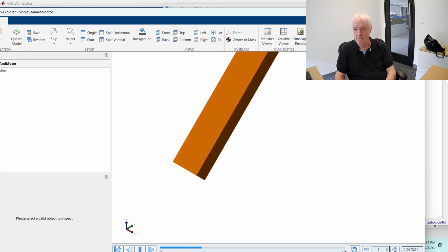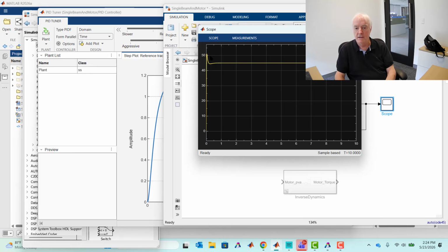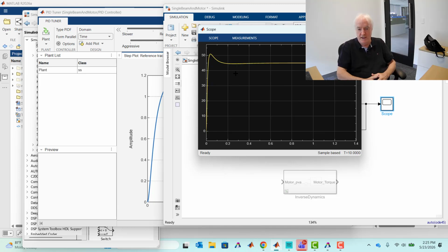And that looks pretty good. Right. And absolutely there's an overshoot. And perhaps that might bother you a little bit, but it probably doesn't if you're really working on a problem the way I am, because we basically made an impossible request. We said at t equals 0, we know your current angle happens to be 0, and we're telling you we want it to be 45.